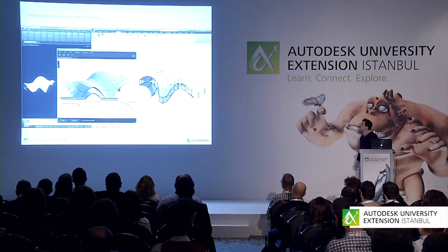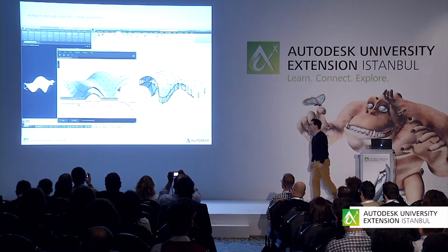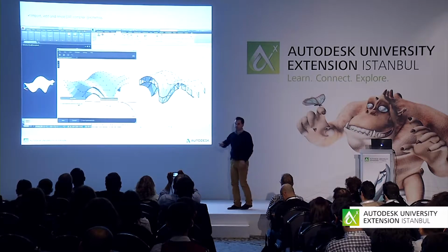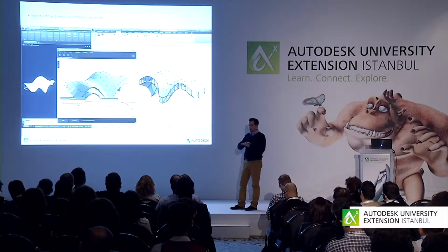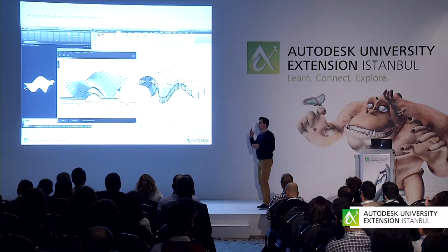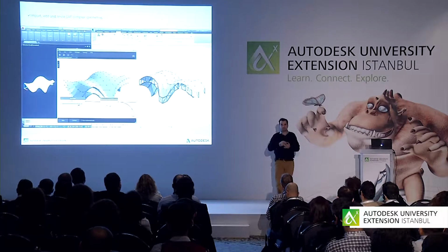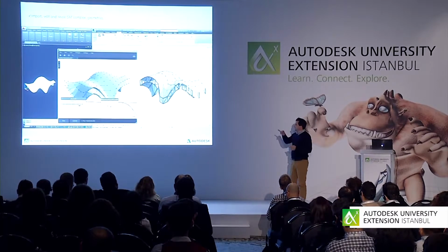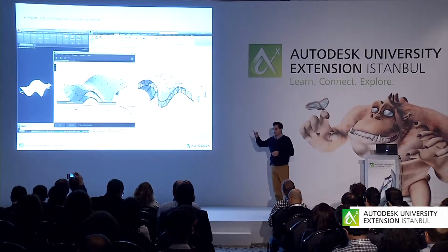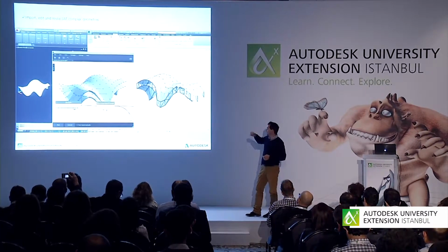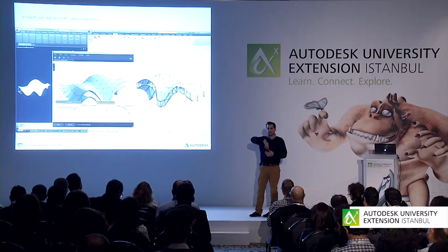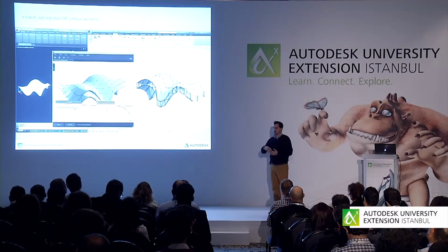Okay, another example shows a surface created in some other software. You can create it in completely different software, like Alias, Fusion, Maya, whatever you want. Then this surface, if saved in SAT format, can be taken by Dynamo. Then you can extract thousands of different pieces of information. You can edit this surface and modify it a little bit.